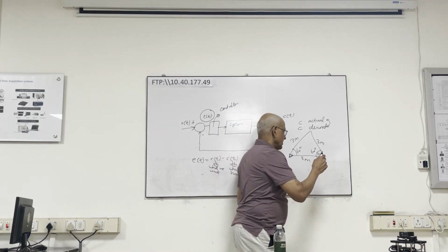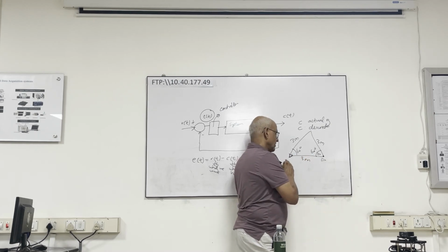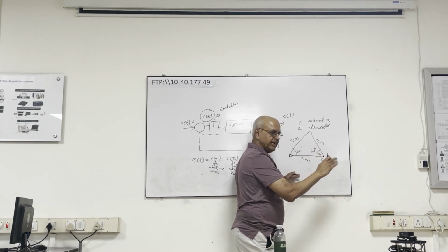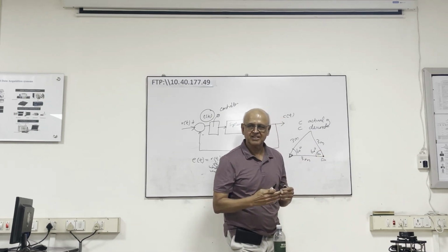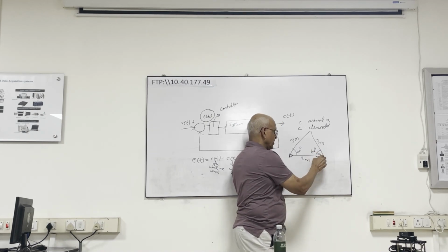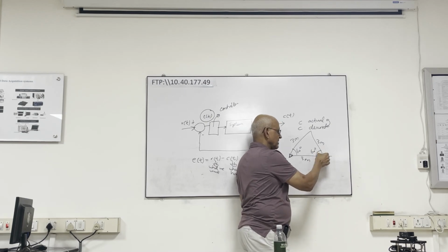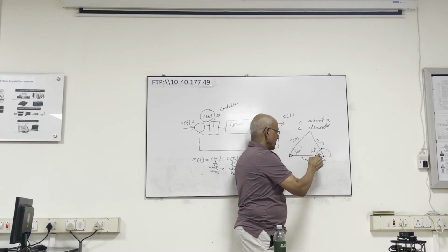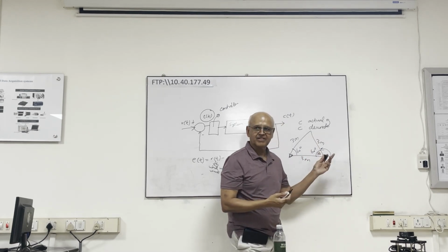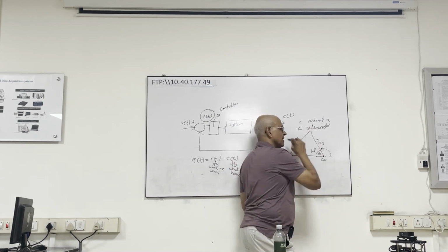And that's a problem, because immediately you won't be able to recreate the triangle. Let me back up and say, how would I drive it in a very crude manner? I would go forward 3 meters, not forward towards this node, just forward 3 meters, because I trust my forward. So you'll end up in different places, right? At that point, I'm going to turn through 120 degrees. It's not 60 degrees. You have to turn through this angle. So then I'm hoping I'm pointing to here, but already you're off. And then I'll go forward 3 meters. You're probably going to end up somewhere here.